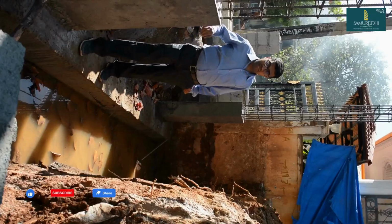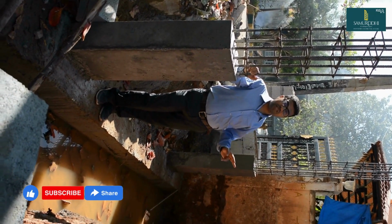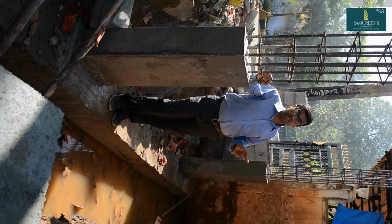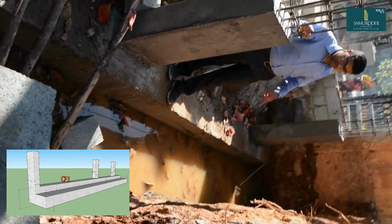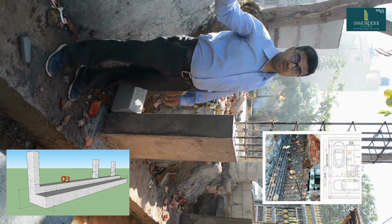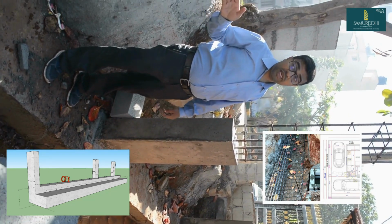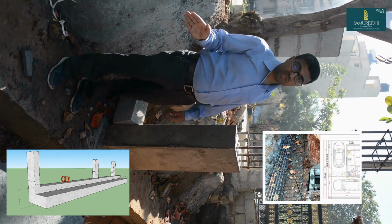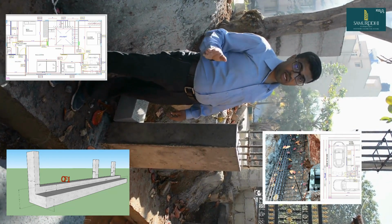Friends, we are now going to see the third kind of footing that we have done. We are at the edge of the site towards the road, and in this stretch we have done 3 columns at the site edge. Why we have done the 3 columns at the site edge is, since our plan was to utilize the parking place to the fullest extent, we didn't want to place the column 2 feet inside the site, which could have disturbed the parking.